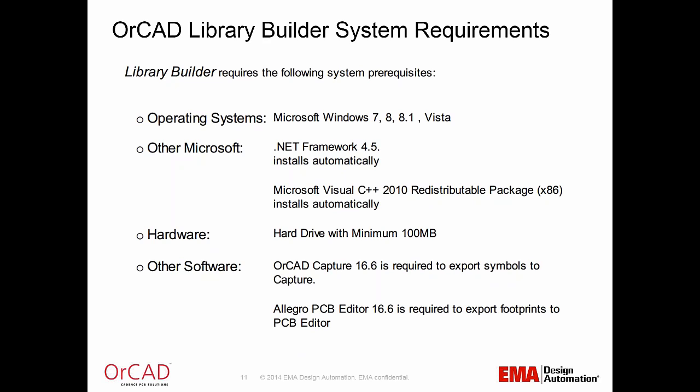OrCAD Library Builder does require Cadence 16.6 or 17.2, the new release. Its licensing is managed by the Cadence license manager that's already installed on your machine from the previous Cadence SPB or OrCAD products installation. In order to run OrCAD Library Builder, you must have a valid license issued by Cadence, and to create footprints, a license for the PCB editor is also required.